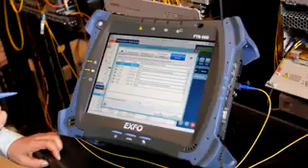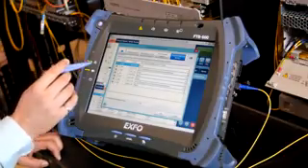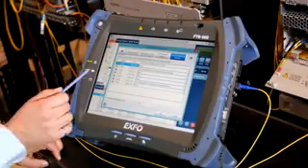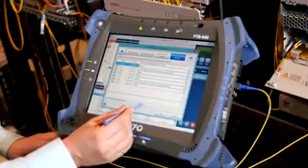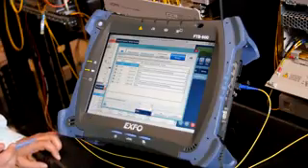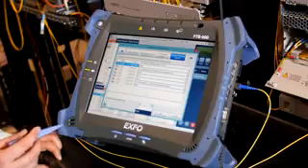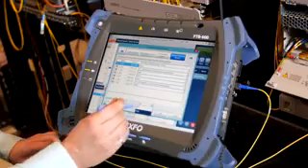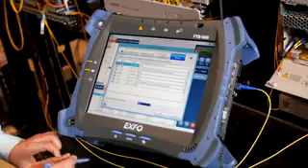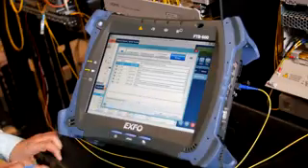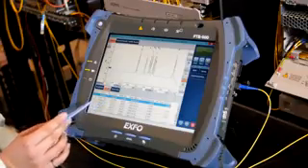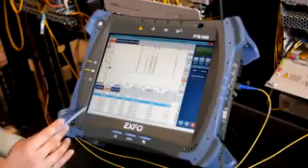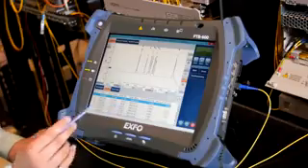Last step, channel matching review. The OSA associates channel 2 and channel 6 with the two traces with the channels off. I can decide the type of analysis I want, either the CCSA, the standard from China, or the IEC standard. I will choose the IEC standard, the newer one, and I hit OK. And then I get my OSNR results here for channel 2 and channel 6 based on the IEC standard.